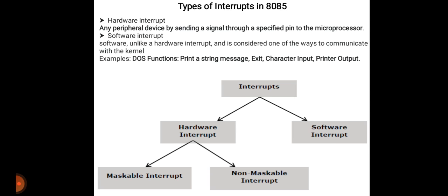The 8085 has a multi-level interrupt system. It supports two types of interrupts, that is hardware and software. Hardware means some of the pins of 8085 allow a peripheral device to interrupt the main program for input and output operations. When an interrupt occurs, the 8085 completes the instruction it is currently executing and transfers the program control to a subroutine that services the peripheral device.